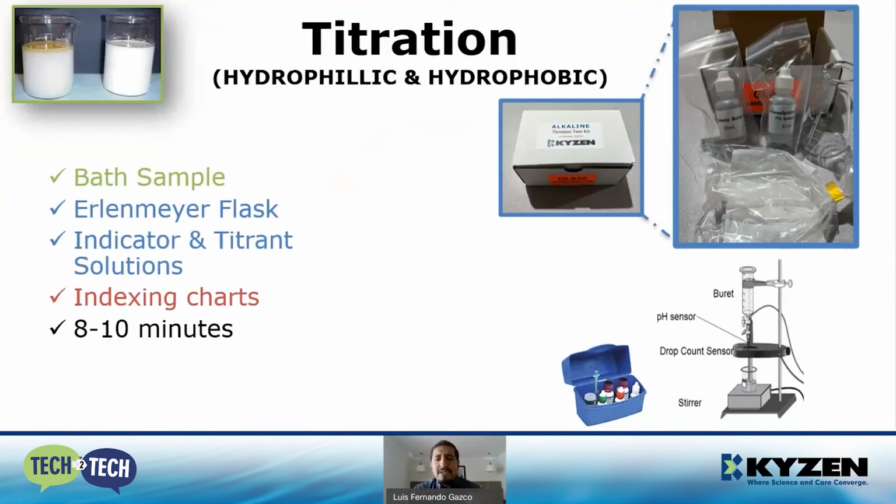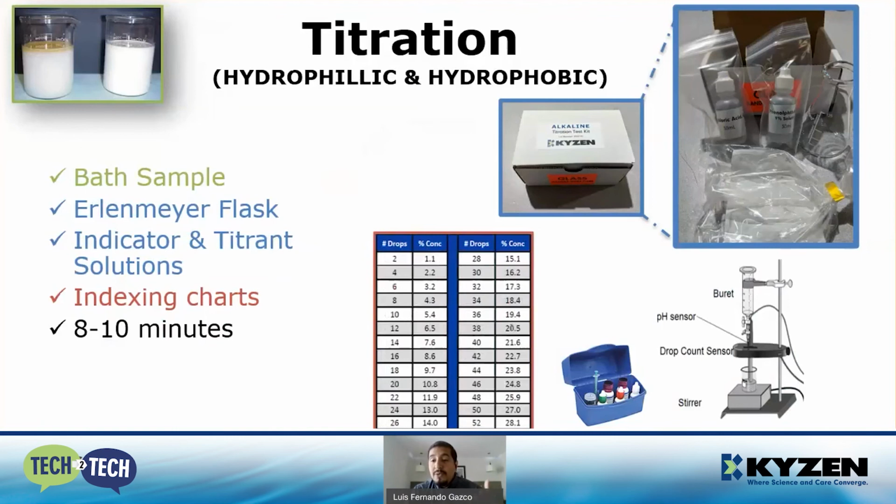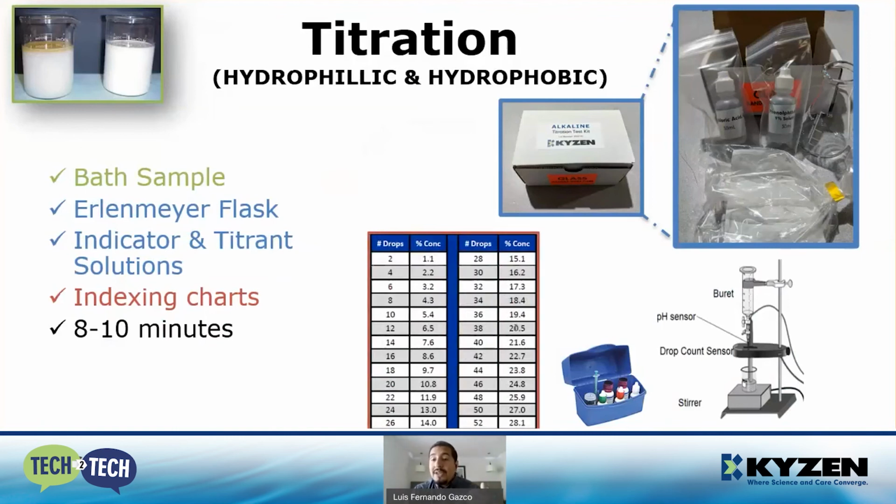It is very important to keep count of the total number of titrant drops required to eliminate the color. This number of drops will be converted into the concentration value using the indexing charts. Though this is a very precise method, it usually is not suitable for on-floor production monitoring, though it is always an option for both types of chemicals.